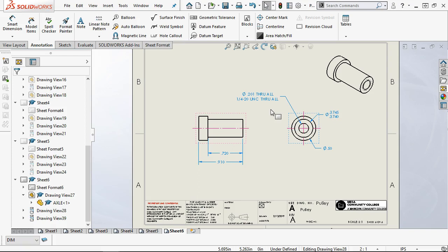It's a standard spiral point. All right, now we're going on the tooling side, and I'm deciding for the machinist what he needs to do. But I'm giving him an out that, hey, I know that this can be manufactured. If you've got to order a tap, I understand you're going to charge me for it. If you need a neck down, if you need a specialty item that will reach, or an extension, then it becomes part of the game. It becomes part of the process.